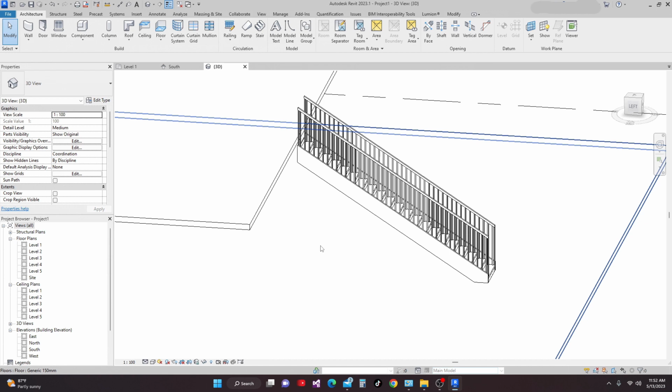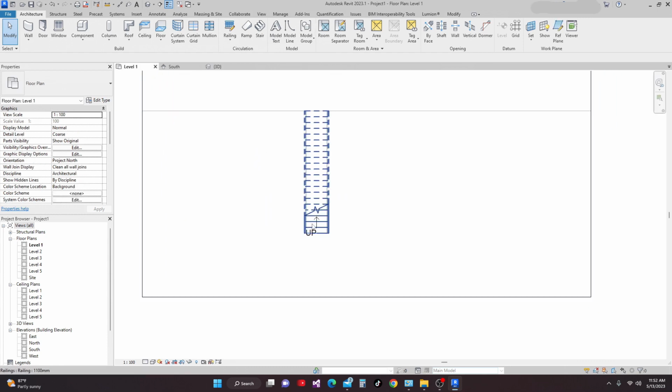This means that if the height reduces, the riser count will remain, but each riser will be shorter. In other words, the footprint or plan of the stairs will remain unchanged. Just as you can see here in plan, the footprint remains the same. It did not change. Only the height changed, and this total height divides the risers, and that is our total. Also, the total risers will not change. Okay guys, that's the meaning. We need to be familiar with these rules of the stairs.